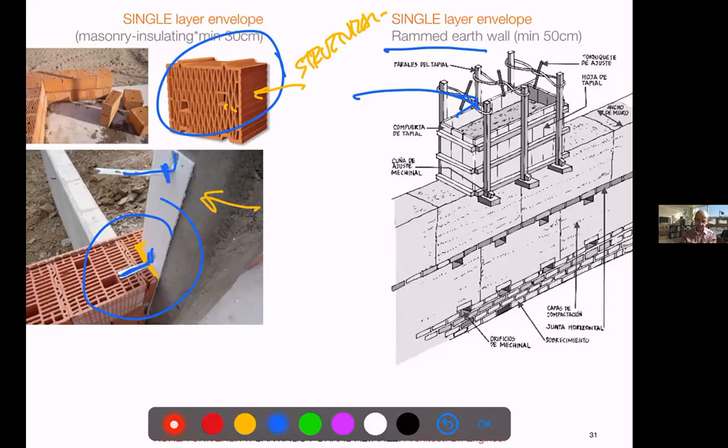It will move. So the few millimeters of differential movement, the uneven settlement or wind or just the expansion will be absorbed by this plate, which is thin and elastic, and it will not have cracks, will not force the weakest element, the masonry, to crack. Interesting thing, and this is a usual exam question.